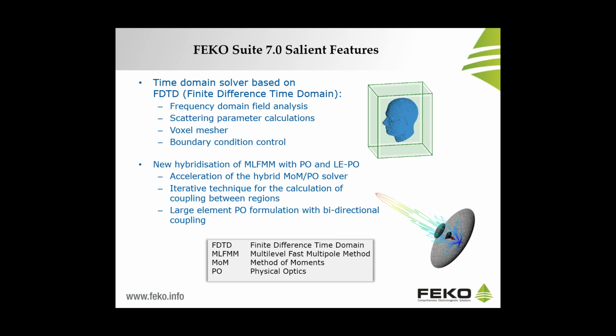And on the other hand, we have been presenting the new hybridization of MLFMM with physical optics and large element physical optics, which is an acceleration of the hybrid MLFMM-PO solver. We have the iterative technique for the calculation of the coupling between regions, as we have shown to you. And also, the large element PO formulation includes bidirectional coupling.